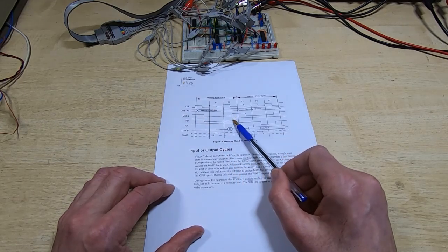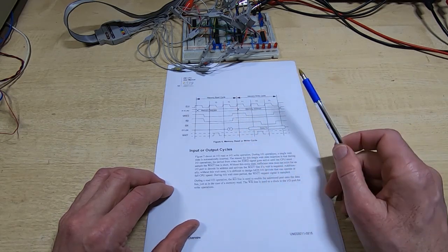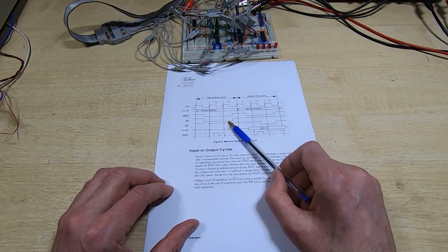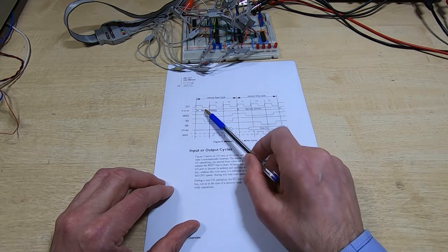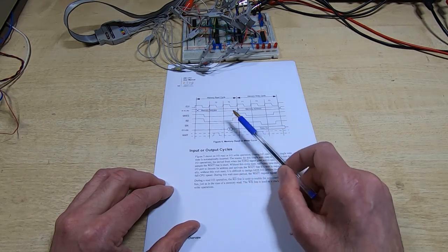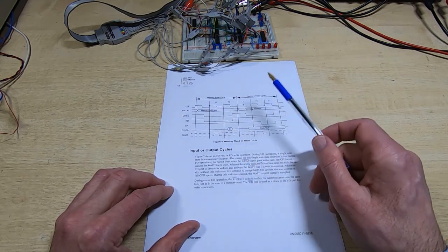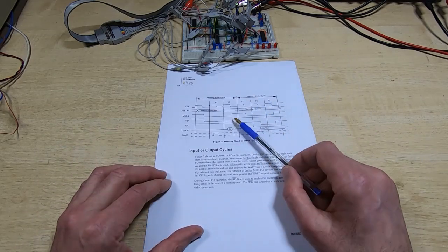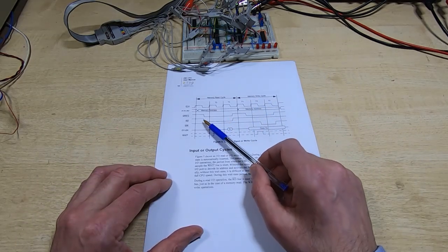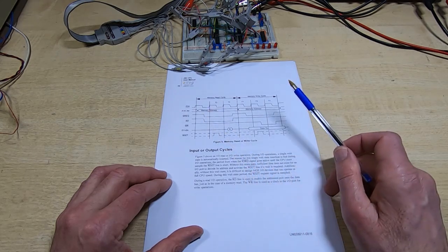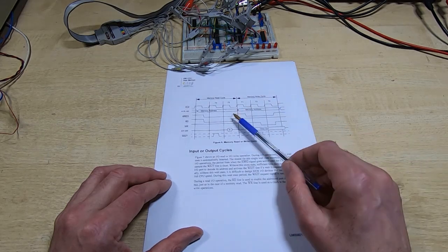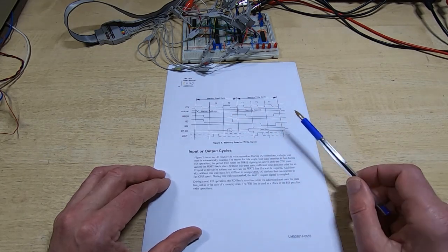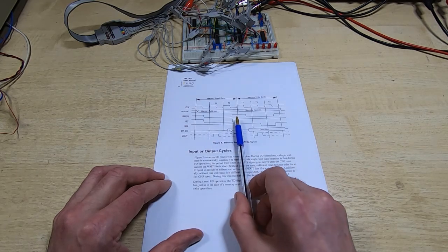Now these lines of course are already connected to the memory system, the decoder, etc. So we can make use of them because they've been released by the Z80, but we do need to make sure that we adhere to the same timing, because our memory circuits, decoder, everything else, the DRAM in particular, has specific timing requirements. We do need to make sure we adhere to that and do exactly the same thing that the Z80 would do, same sequence, same timing. So it looks a bit complicated.